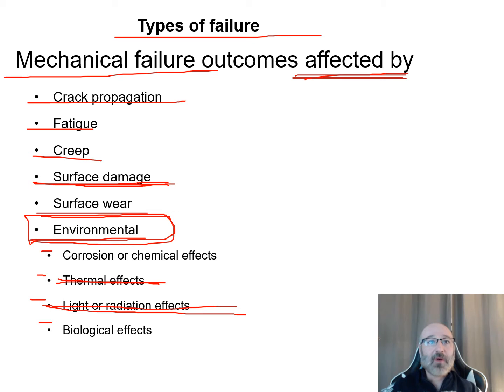And then we've got to think about the environment right here. Is it a corrosive environment? Are we going to be near the ocean? Is there going to be salt that could affect it? Maybe this is not even just the ocean, but maybe this is in the Northeast where we have brine that we're using, and it's part of a car right there. And all of a sudden, you're going to have that salt water coming up on that part, or that system right there. And is that going to be an effect?